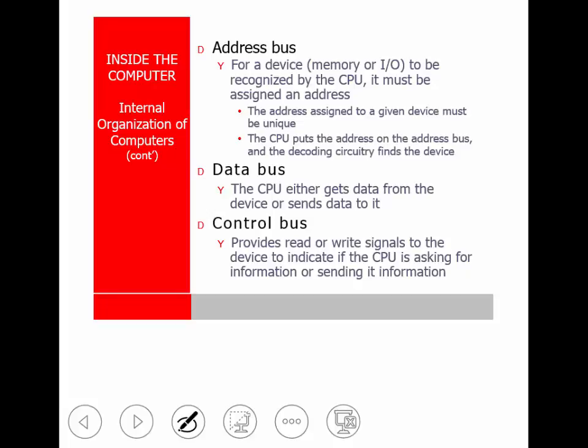Because the address bus, let me just point out, with few exceptions, the only one that writes to the address bus is the microprocessor. He's the only one. He controls the show. The data bus is bidirectional, and it's very tricky when you deal with the data bus because every memory chip, every I/O chip, and the processor all can write to the data bus.